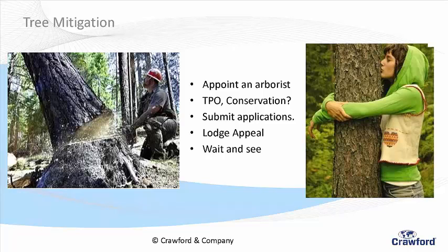So with that, we need to do an application. It's not like a planning application, but if you're going to apply to get the tree down, you need to have evidence, don't you? So what's the evidence you need? The roots, the sample of clay. You're going to need monitoring, aren't you? So I come and see your house, and you tell me there's a TPO or it's a conservation area. I can't even apply to take the tree down for possibly another year. Think about it.